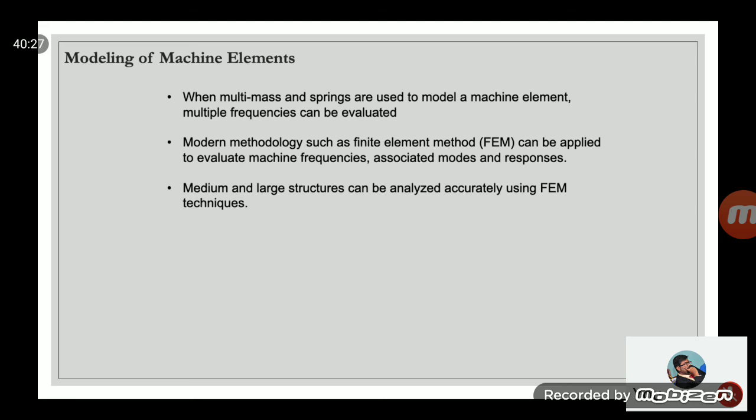So the modeling of machine elements is multi-mass. In that case, we have to use modern methodology such as finite element methods in order to get all the frequencies and associated mode shapes. You need the mode shapes also, in order to understand what's happening to the system, because you have node points in the mode.